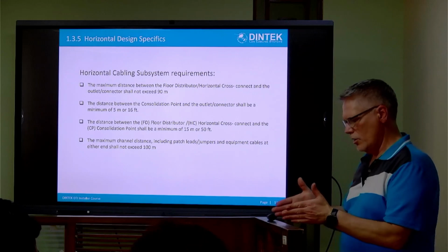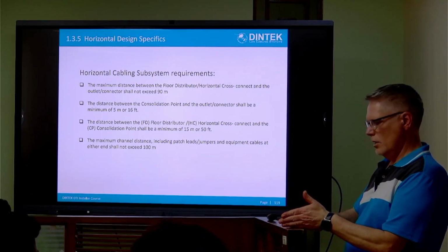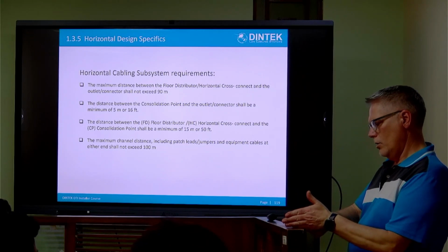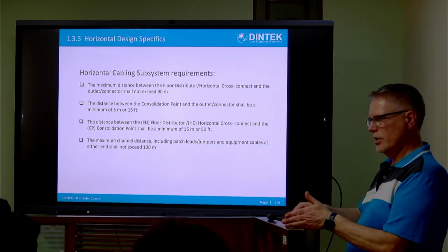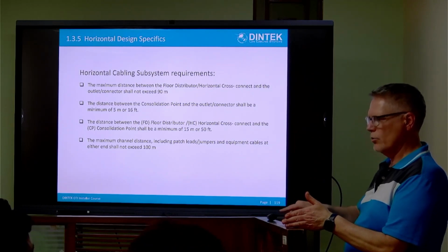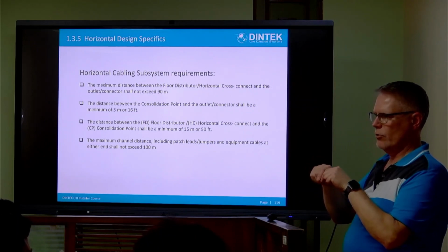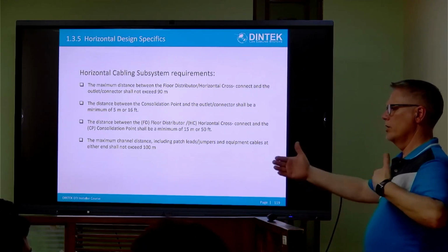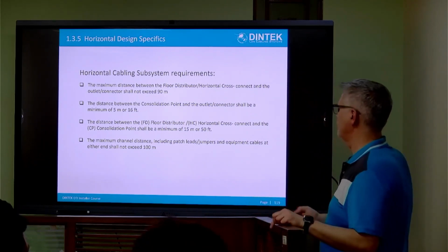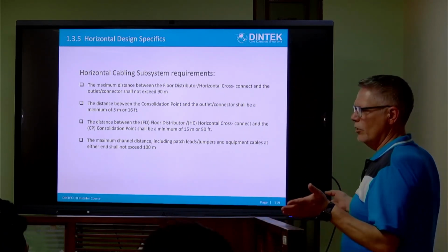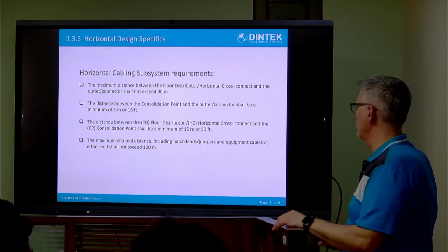So if you've then got a connection point at say 5 meters, and the power of the signal is hitting that connection point, it's going to be creating more near-end crosstalk. So you're actually amplifying the amount of near-end crosstalk that's happening. So you always try and keep that distance out to about 15 meters. Sometimes it might not be possible, but as a rule, try and keep it to that minimum of 15 meters.